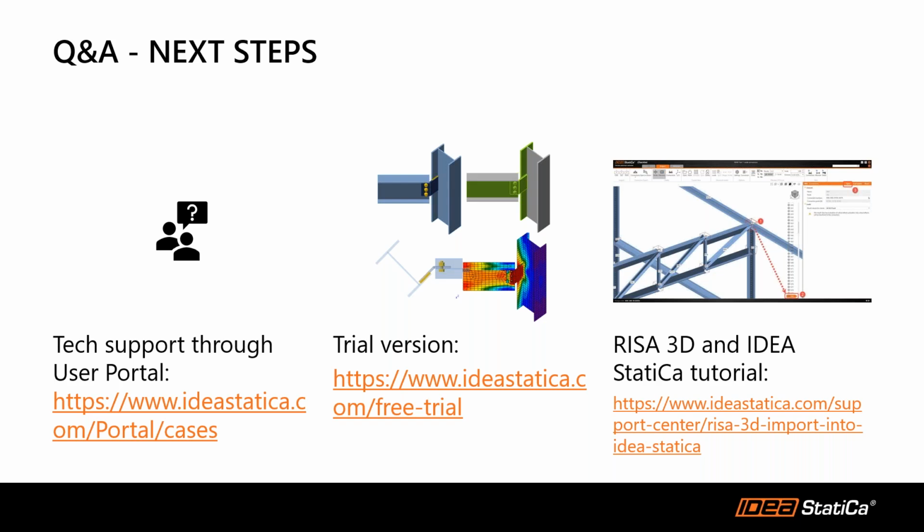Every single member is defined by their vertical vector, so it's y by vector. If we were to do that export with y by vector, the members will be rotated horizontally because in IDEA Statica, the y-axis is horizontal. So that's why we're changing it to z by vector, so that when it gets to IDEA Statica, it's on the correct vertical axis. Okay, great.